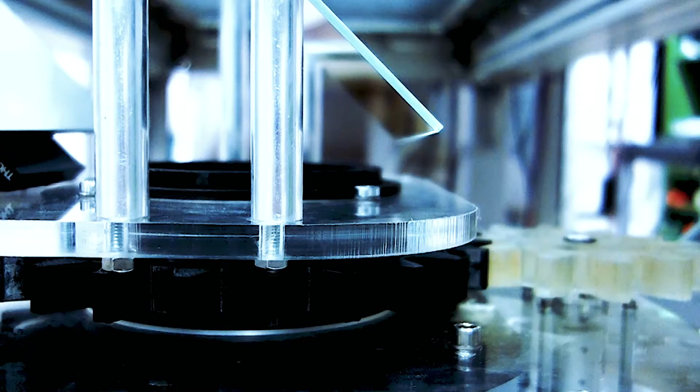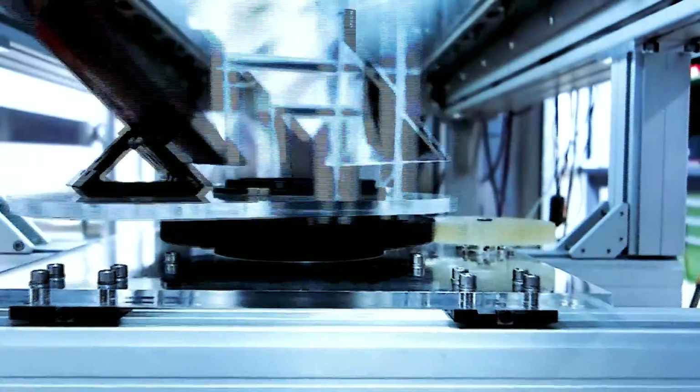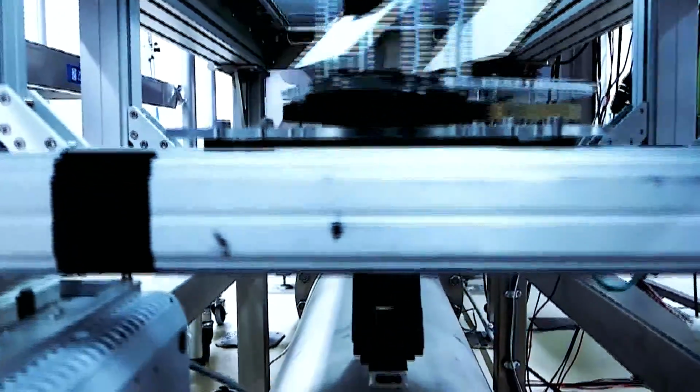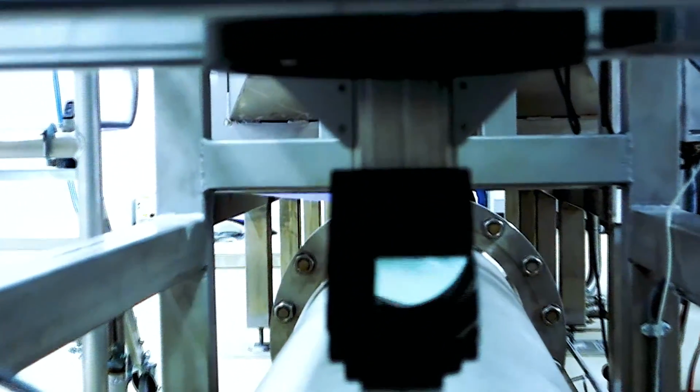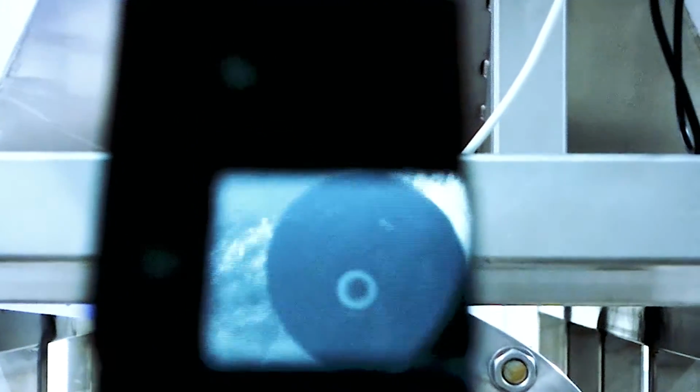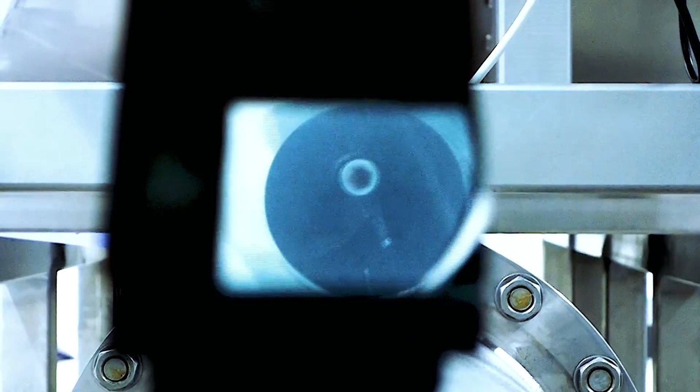To obtain flow measurements with satisfactory spatial and temporal resolution, we assembled a spinning mirror apparatus. 2 45-degree mirrors are rotating about an axis which was aligned with the turbine's axis of rotation. The outer mirror is placed at the same radius as the turbine blade and reflects its image onto the central mirror. The central mirror reflects the image downwards through a hollow shaft onto a third stationary 45-degree mirror. The camera looks into the stationary mirror, capturing a close-up image of the developing flow every millisecond.